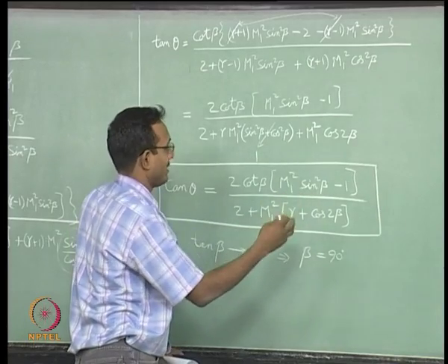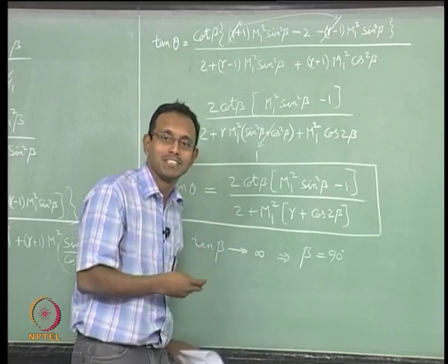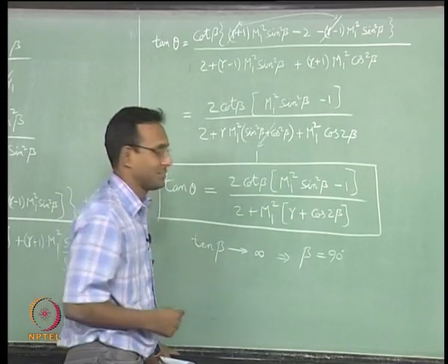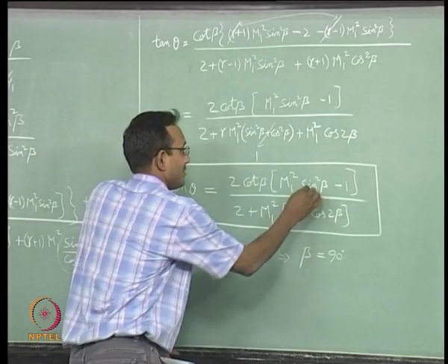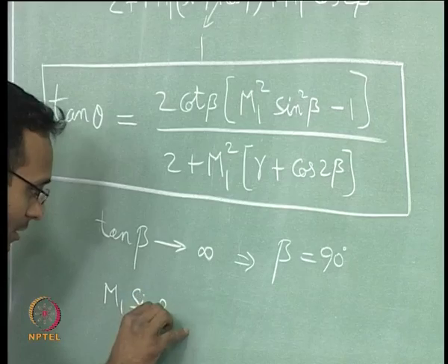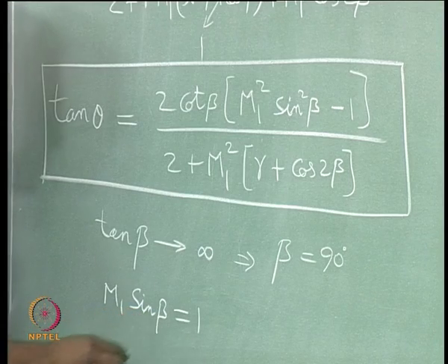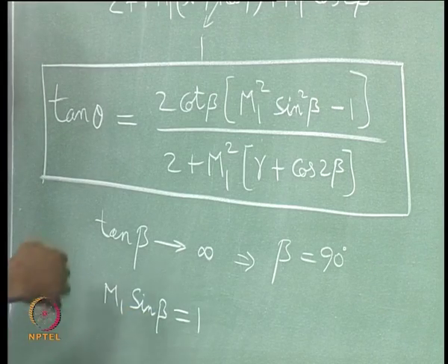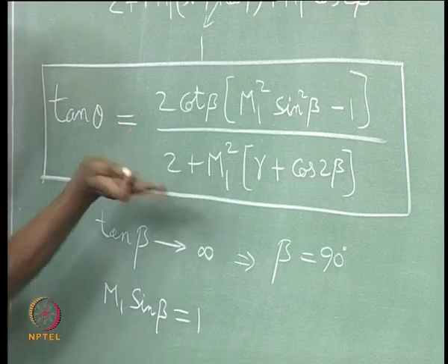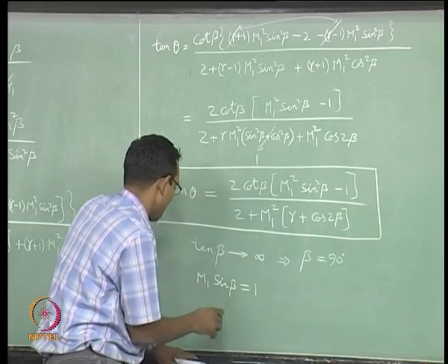So I will take a square root of that, it will still be 1, plus minus 1, minus 1 is not possible. So, we will keep it as plus 1. Minus 1 just simply means that the flow is from right to left instead of left to right. Mach number negative does not make sense for us, it is just absolute value of velocity for us. So, I will just have one solution for it, M1 sin beta equal to 1. Minus 1 just simply means that I have either a negative angle beta or I have a negative Mach number, which means flows from right to left. Negative angle beta is the shock, instead of like this it will be like this, that is all, that is nothing great. So, we will come to that situation later, we will not call it negative beta anyway, we will keep it like this.